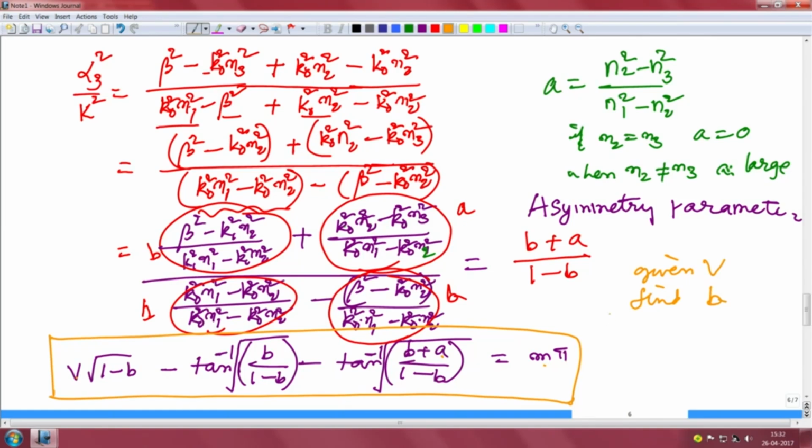So, let me draw and we can interpret the modes of the waveguide, and before going further we can discuss the nature of the modes. So, the V number on the x axis and b on the y axis, and of course, before you do that we can form a table of values of b versus V by programming or whatever way, and we can note that we get curves similar to what we obtained for the symmetric slab waveguide, but there is a difference. We will note that soon.